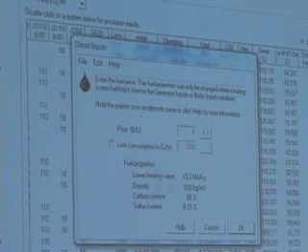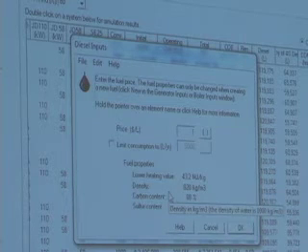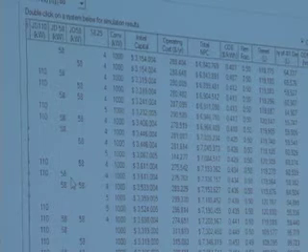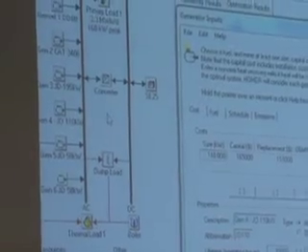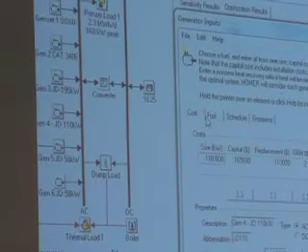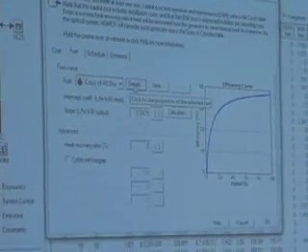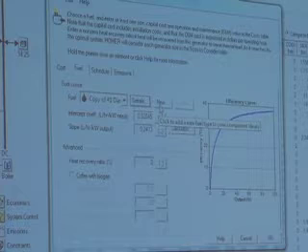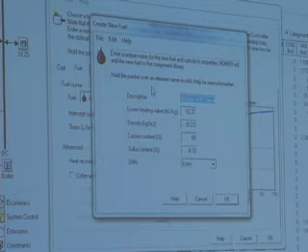Here's the properties of that fuel in metric, something else we're going to change in version 3. But to create a new fuel, you go into the generator that's going to use that fuel, and you go to the fuel tab of it, and this is where you create a new fuel. So here's the details, the parameters of that particular fuel. But if you want to create a new fuel, click on the New button.